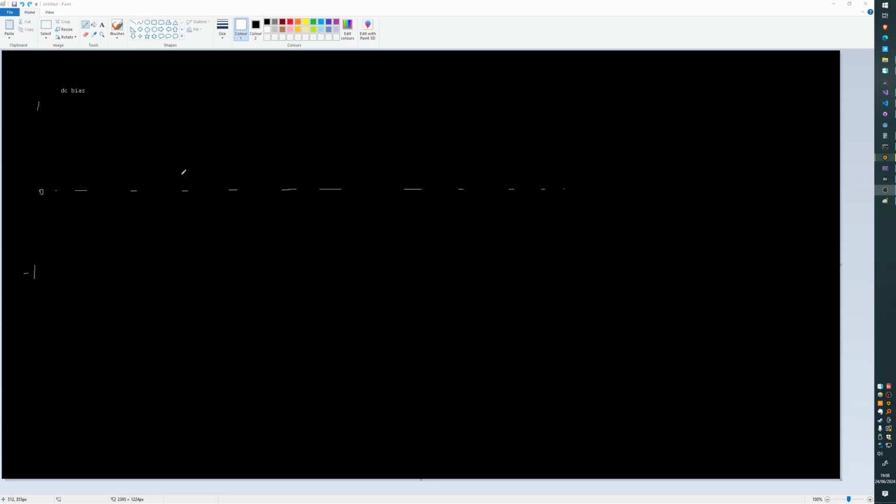So the problem with using a high pass filter to correct DC bias is the filter introduces a little bit of delay, which is not the end of the world, but if you're doing sample analysis stuff, and part of the reason I'm revisiting this analysis now is to try to improve the quality a little bit and make it more accurate as best I can, I'd rather do it without introducing any delay.